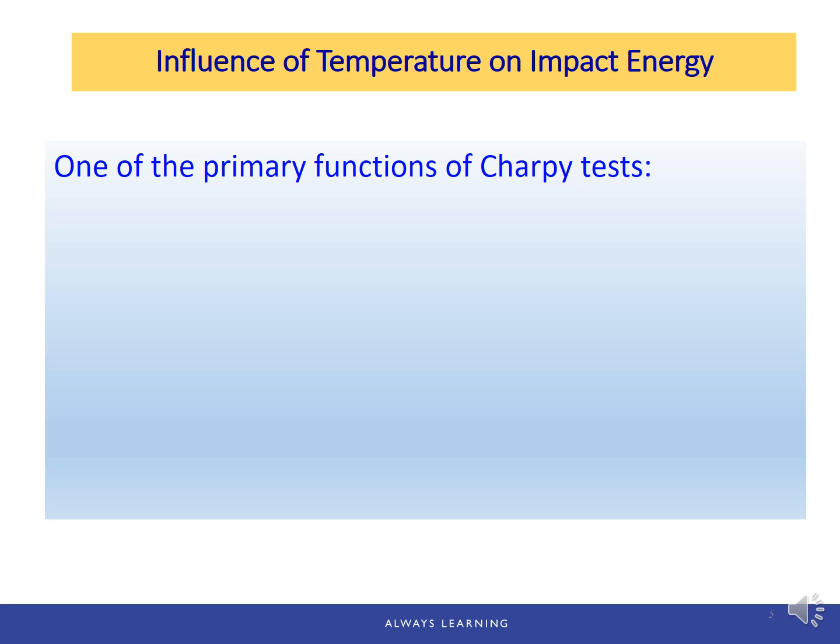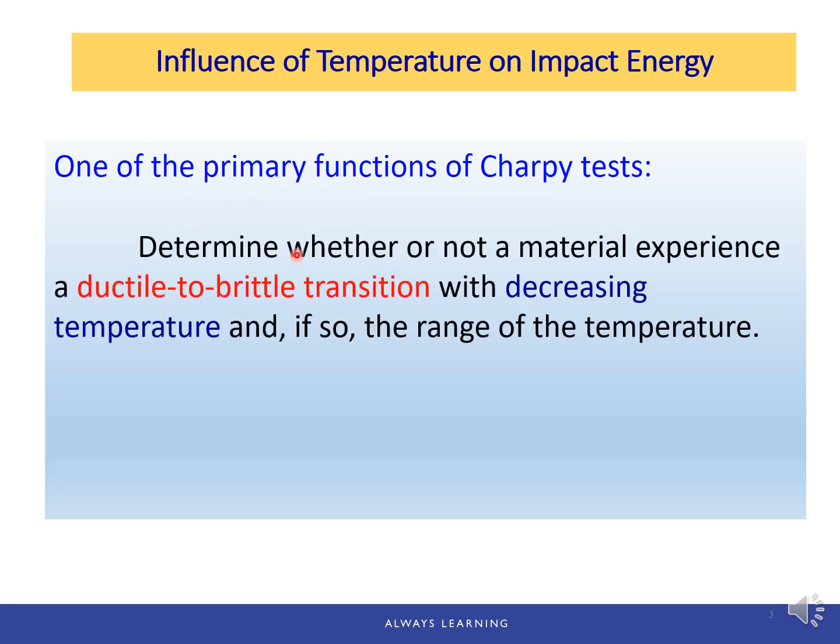Perhaps one of the more primary functions of the Charpy test is to determine whether or not a material experiences a ductile to brittle transition with decrease in temperature, and if so, the range of the temperature. This phenomenon, the ductile to brittle transition, we have seen earlier. If you still remember the pipe, right?